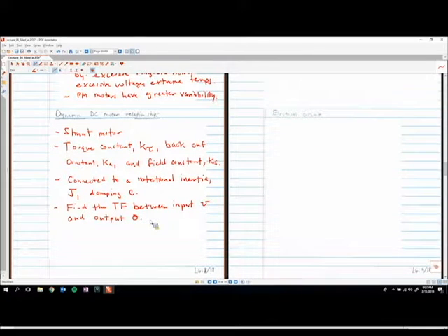we want a mathematical relationship in the frequency domain between the input. So this would be, say for instance, I had a motor sitting on my desk that's attached to some sort of rotational inertia, and this motor and inertia have the parameters that specify the problem. I want to know if I put a voltage of basically any type, right? So say I can somehow structure what this voltage looks like, a sine wave or a pulse signal or something like that. I want to know the Laplace transform of the output, which is motor position, right?